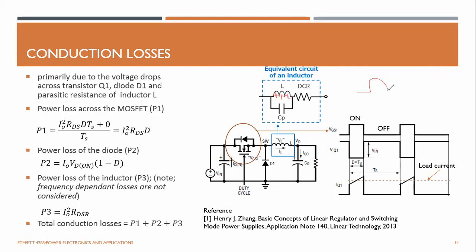If you build a coil like this, there is a parasitic capacitance between these two segments, because in any coil, when the charge is passing, some kind of capacitance occurs. That is called parasitic capacitance. It makes an equivalent capacitance in the picofarad range, a very small value.